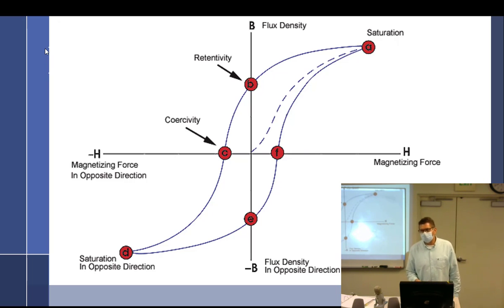But then if I tell you that you can also demagnetize stuff with DC or step down current, you'd be like, well, why does that work, a step down current? If you magnetize it at this level, we already magnetized it here, and then you apply a current that's lower, that shouldn't have any effect on it, right? But it does. So that's where this hysteresis loop comes in and explains what's going on.